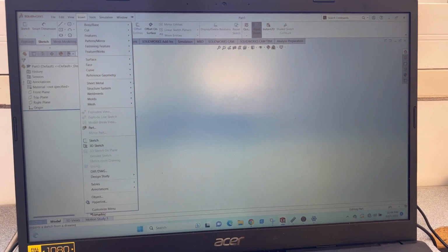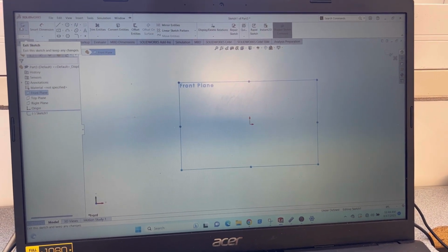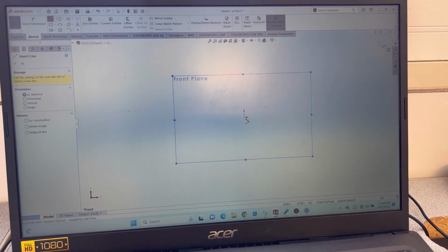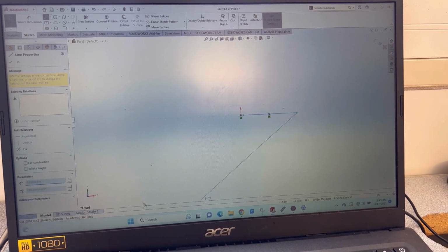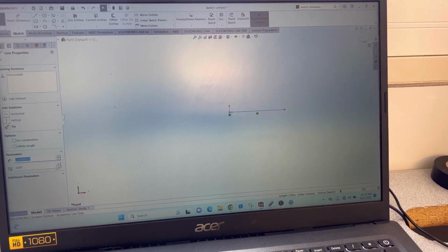All right, so we're gonna go with your front plane and click sketch. You're gonna click your line, and we're gonna make the part 3 inches.